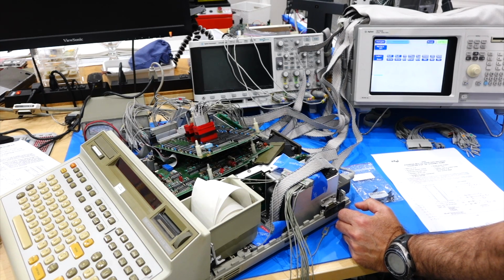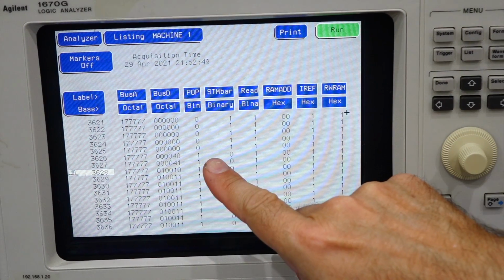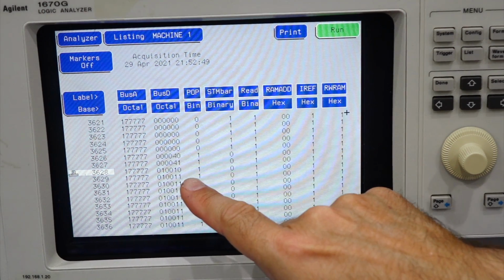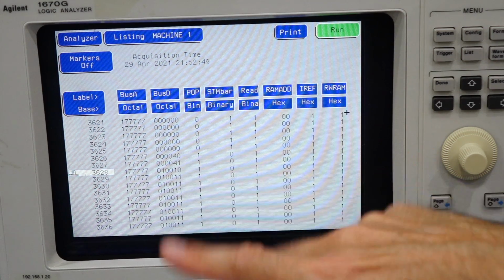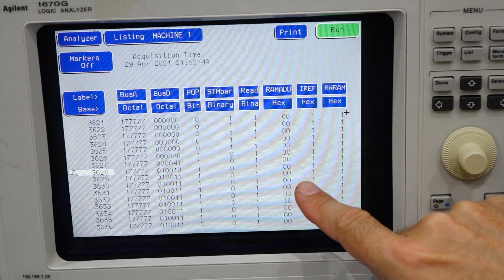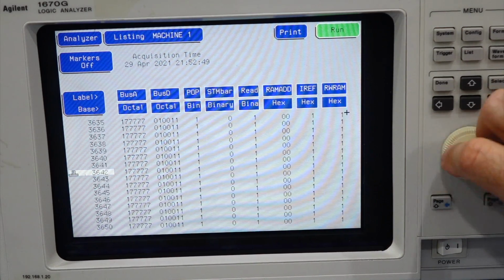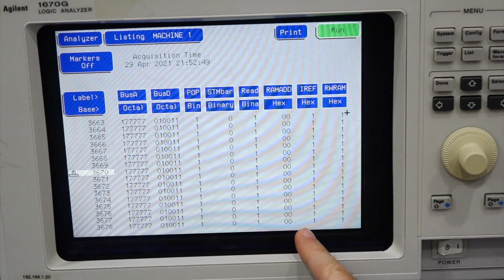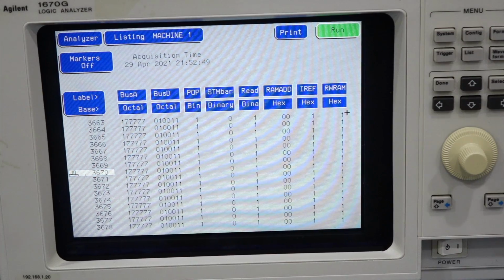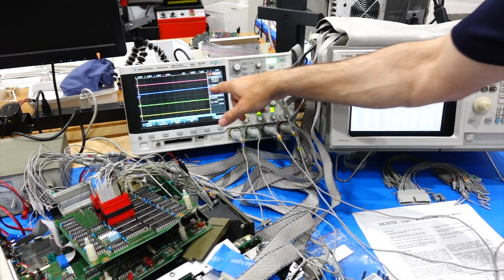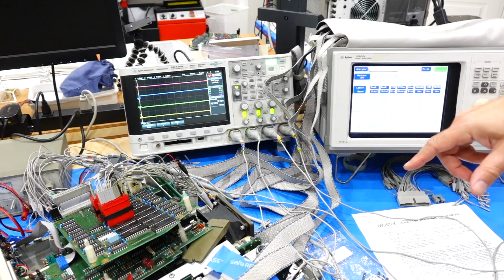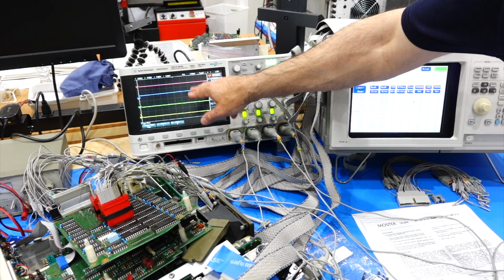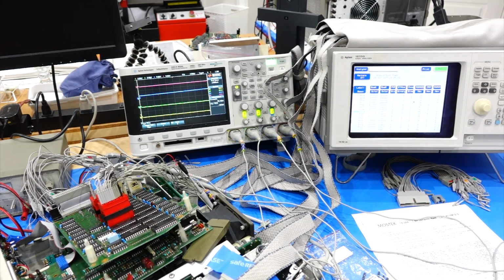Okay, captured a few. Okay, eventually it starts. It was 40, 41, and then it went to 10,000 something. It's stuck in a RAM checking loop, but I see no refresh address. Nothing, still 0. Or it might be that my Intel chip is so zapped that it doesn't provide any address to the RAM. So I've now added the scope to the mix here, and so I have row selection, column selection, and 2 address bits. And see if that wiggles at all.